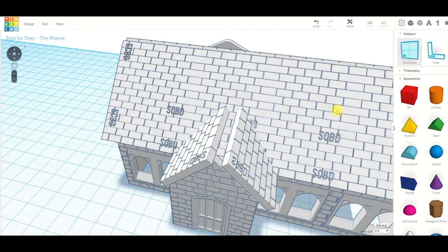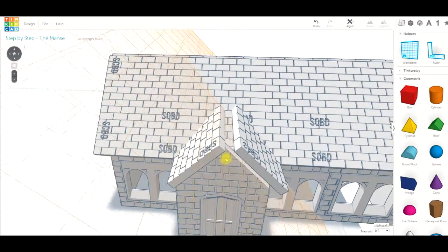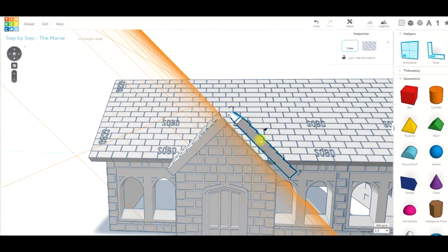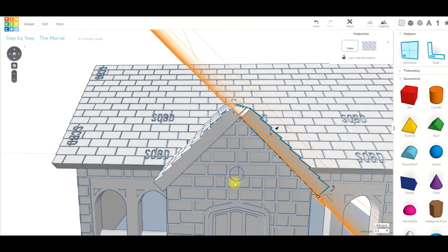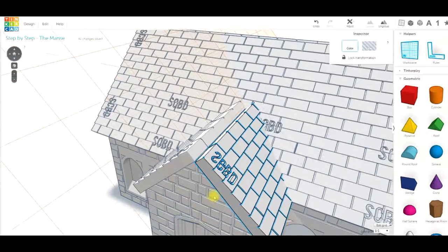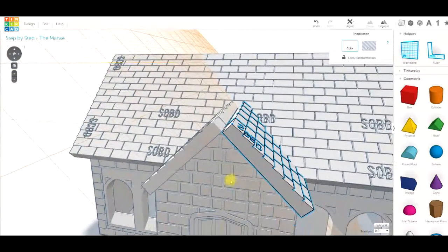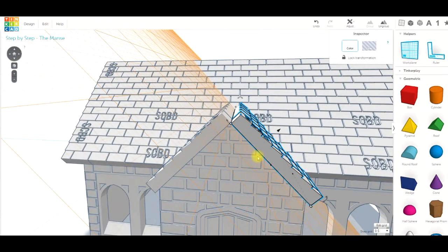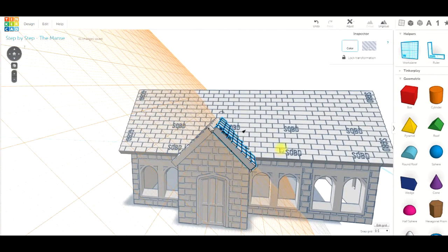Then grab your work plane and just drop it underneath there on this plane, so you know where you're working. If you see, we sat away, so click on there, hold the little arrow and bring it down till it meets 0. And you can use your left keys until you're in plane, and that's where you want to be. Okay, so fine, adjust that, probably go up another notch. There we go, it's even better. Slide away a little bit and just drop your work plane anywhere on the floor.